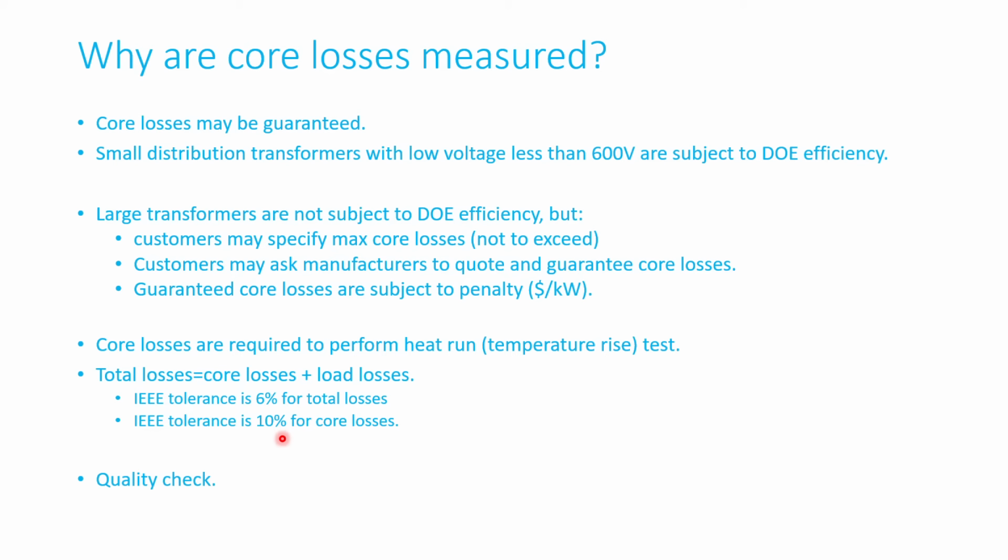Then you have the winding that's energized. You have copper, for instance. Probably some turns are shorted during the workmanship. If they were shorted, it will show up as a high excitation current because you will have circulating current. Or probably you have an open circuit somewhere, so you have some turns out of the circuit. So it's a good check.